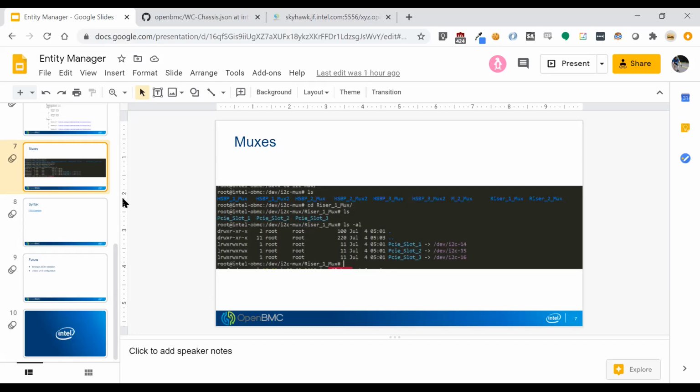I think the earlier questions about how mux support works are really around that missing feature. So what I'd like to see is something that you can't detect behind a mux, but you just think is there. The simplest use case is something like a PCIe expansion card that has an EEPROM on it and also a mux.